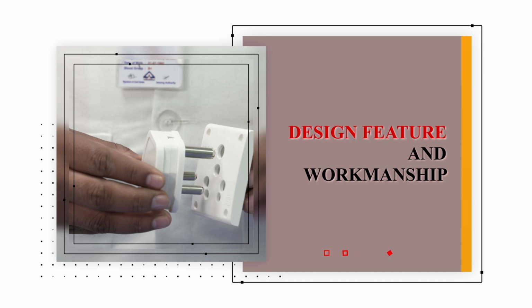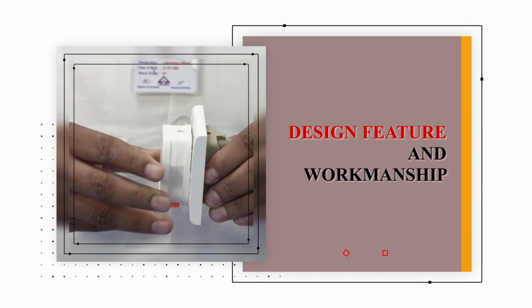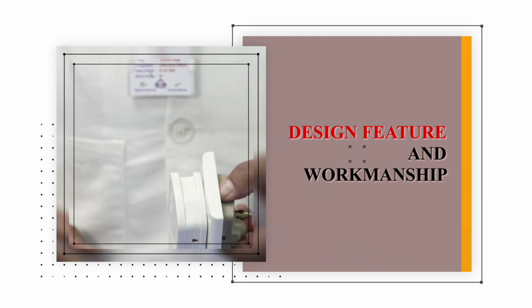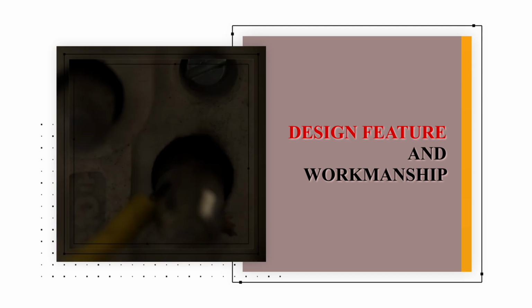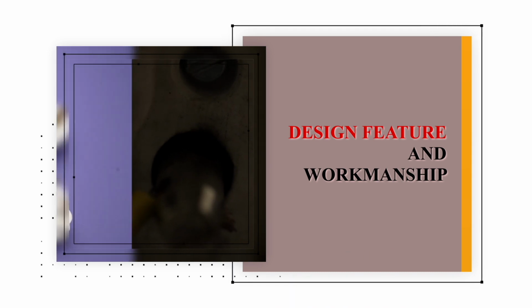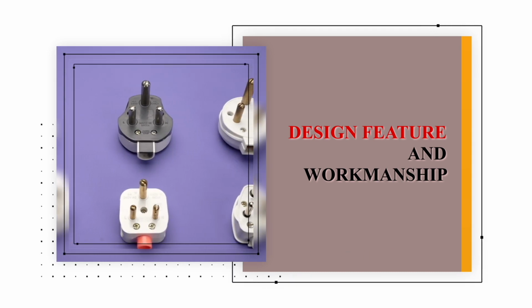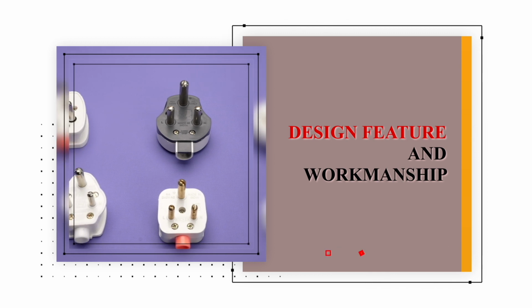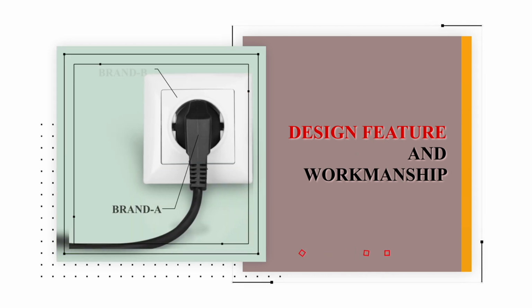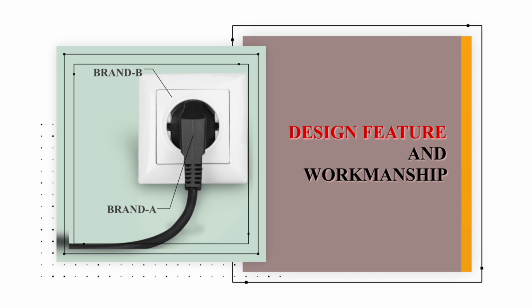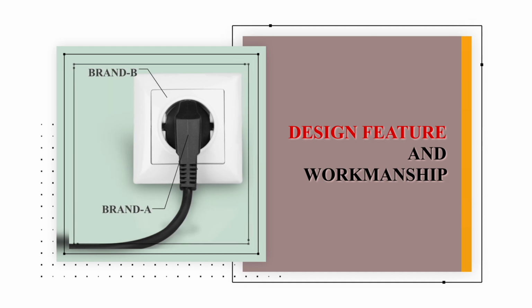The pins of the product should be such that they allow proper fit and do not leave any loose contact. The loose connection can lead to sparking due to ionization of air in the space between them, eventually leading to fire. The plugs and sockets are designed in such a way that they are compatible with each other even if they are from different brands, in order to have proper fitting and to prevent loose connection and therefore sparking.